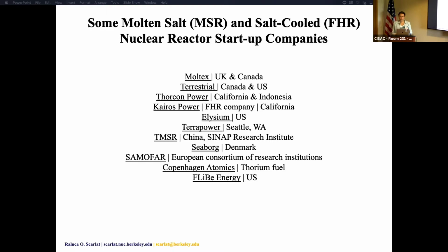It's very much similar to today's reactors that have solid metallic fuel rods and water coolant, but instead of the metallic fuel rods, FHRs would have graphite fuel elements in which there are microparticles that encapsulate nuclear fuel, and the microparticles are a composite of silicon carbide and pyrolytic carbon. And then the coolant, instead of water, would be molten salt.